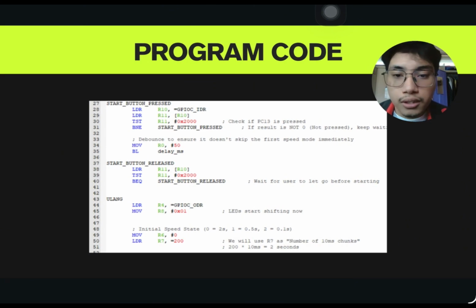So when the start button is pressed, GPIOC IDR is loaded into R10, and then we load the value of R10 into R11, and then the value of R11 is tested whether it is 0x2000, which indicates the button has been pressed. If it doesn't equal 0x2000, it will return back and wait for the button to be pressed.